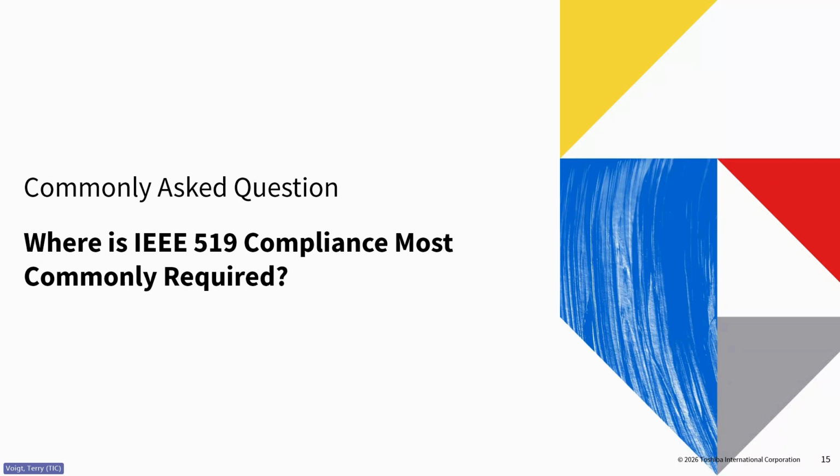The result of that is a lot of times VFDs have some negative harmonic effects, right? So HVAC is a big one, and the other one is the water and wastewater industry. The reason why is we have smaller pumps, like pump stations located throughout the country, or smaller areas. IEEE 519 is important there because the power that they're consuming is primarily on a VFD.